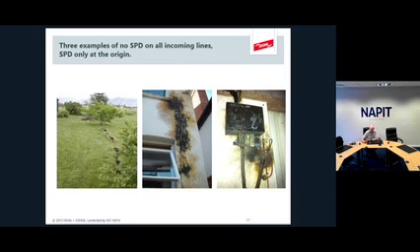So as soon as it attaches to the ring main, that surge goes all the way around the ring main, blowing everything up until it gets to the SPD in the consumer unit. If only the SPD was in the connection unit where that external cable joined the ring main. So that would have been an SPD on the 0-1 interface where the cable left from the inside going outside.